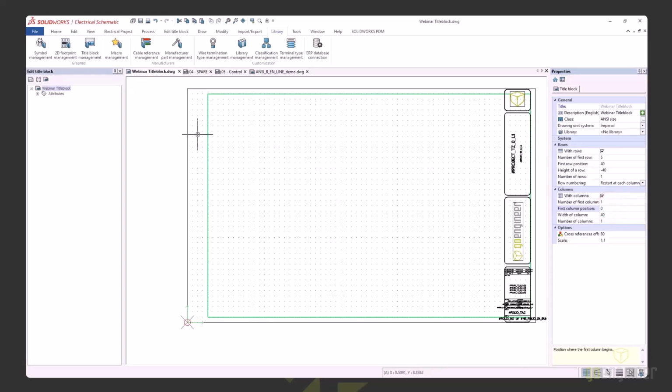The column width is the entire page, so it is a 17-inch column from here to here. And the number of columns I have is 1. Once I have that, I am going to turn off this check mark and save. This ensures that I am only using one column for this entire area and that it doesn't go off of the page.